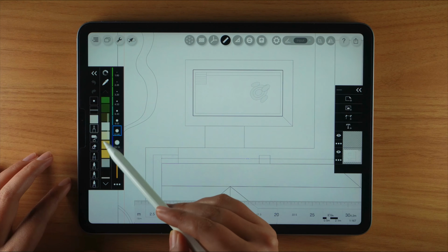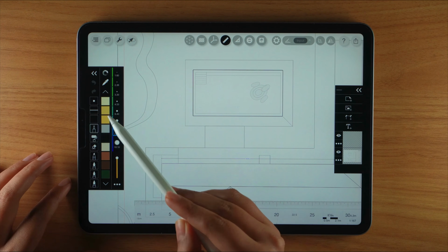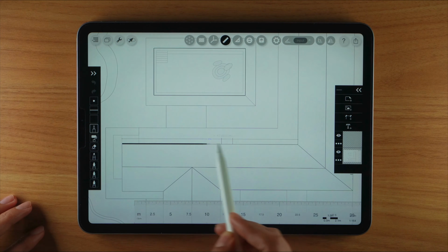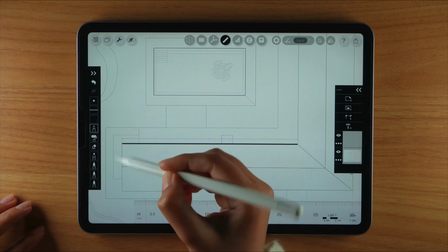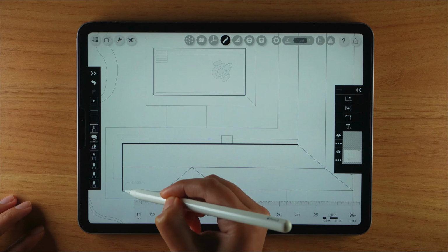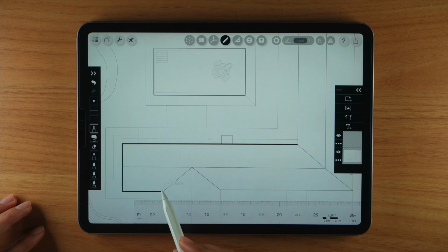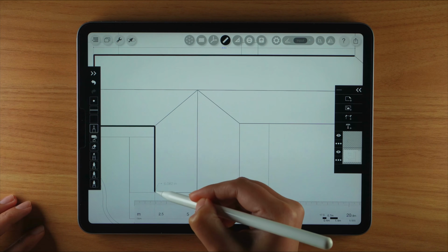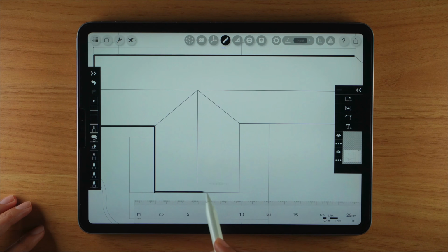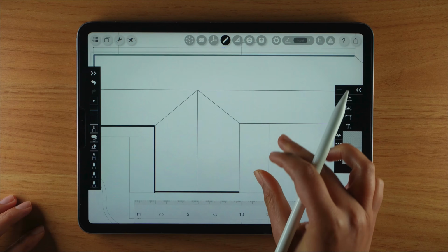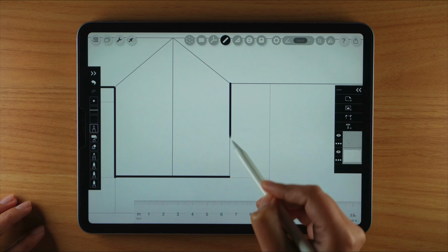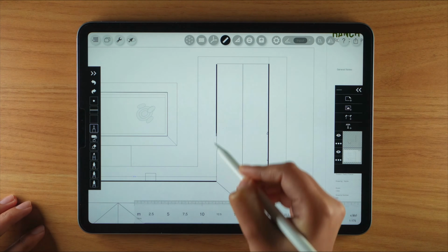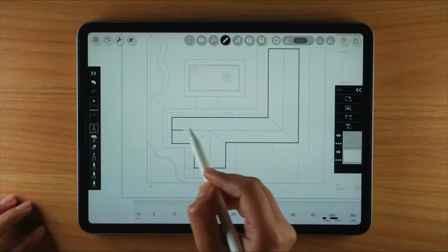Now, using the scale tool, I will select the pen tool in the black color and adjust the stroke size. Then, I will start tracing my building and all the site elements. As you can see, tracing in Morpholio Trace is very smooth. There's also a new feature called line length, and you can see that while I'm drawing a line, it shows the length in meters. We'll quickly trace all the required lines, keeping them at 90-degree angles.